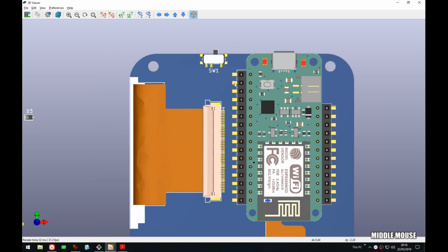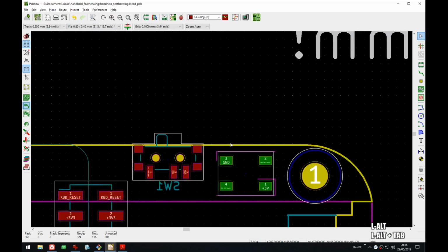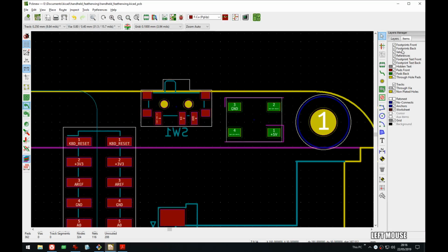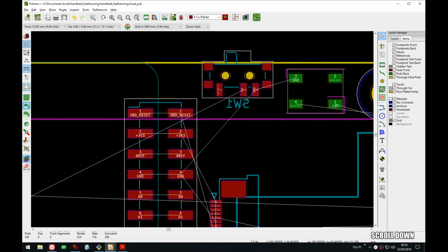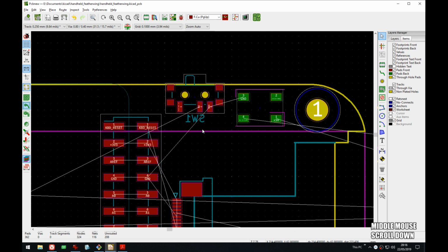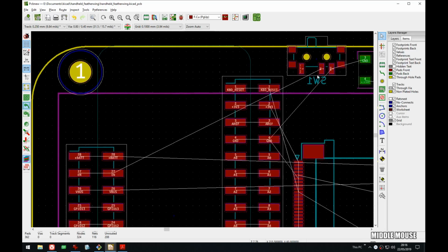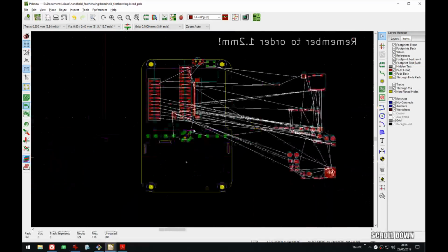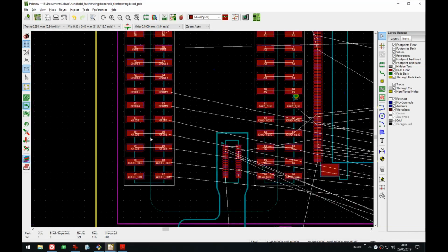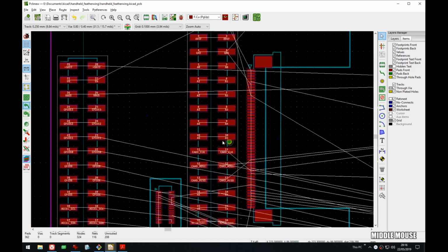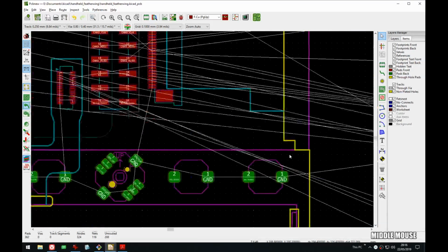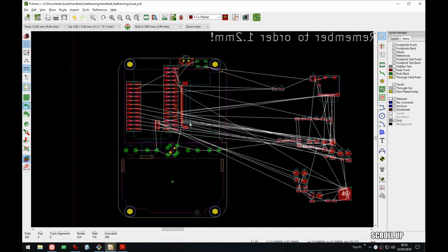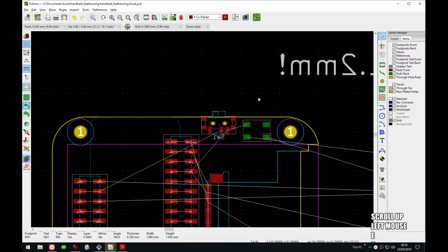Yeah, I think this should be fine. It actually, let's see, layers, no, not hidden text, rat's nest. So it's actually supposed to go to the enable, which is here. So yeah, the routing is right. It would be way worse if it was somewhere there. I think a lot will be decided by the actual, I mean, to ease out the routing, because it's not a lot of components, but it is pretty tightly in one place. So that's gonna suck slightly.